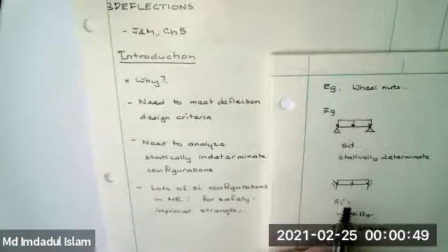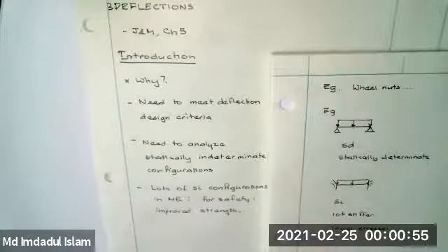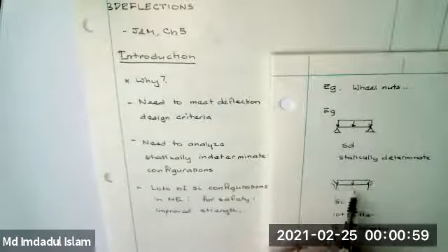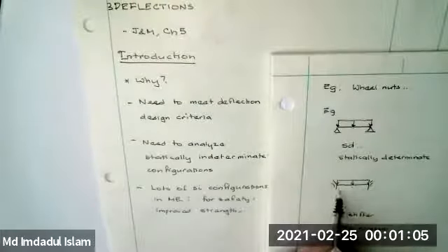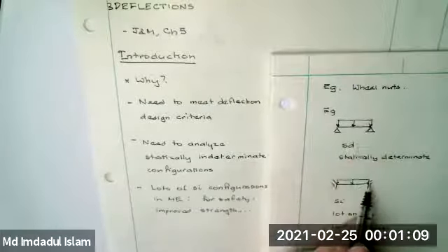You're concerned about weight. You want to keep the weight of structures down because you're moving things. And so you want the things that you're building to not have lazy or too much of a lazy part. That's one of the reasons why you start looking at hollow shafts when transmitting torque and so on. The center part is lazy. This beam is relaxed over here, not doing squat. That's not the case here.